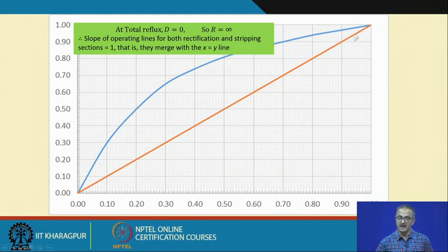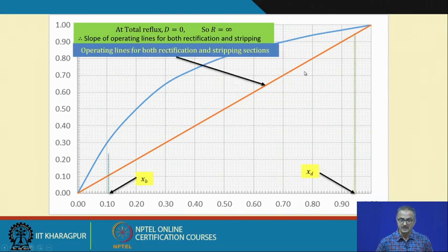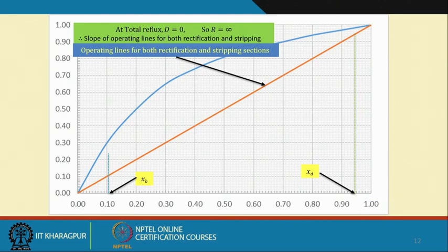So when this happens, because we have taken D as 0, we cannot have any further change in the distillate. That is the extreme we can go to. In this case D is least, and the operating line has now taken the lowermost position as the 45-degree line, so we say that in this case we shall get the minimum number of stages.